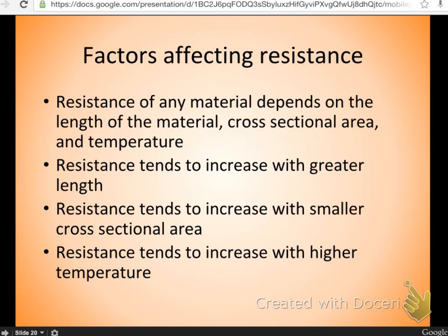Years ago, I had a relay on a Ford Ranger go bad. And if the truck was warmed up and everything was at operating temperature, and you shut it off, it wouldn't start again until everything cooled down completely, and then you could restart it.